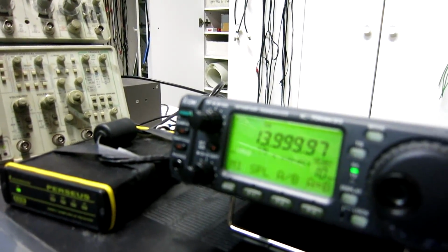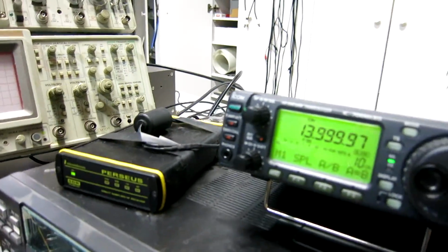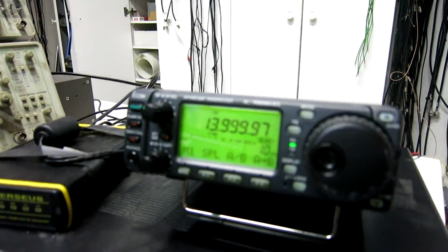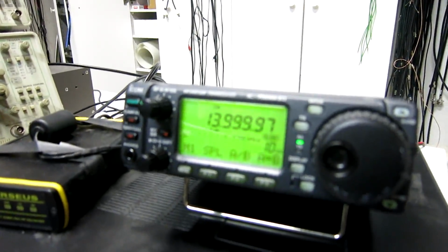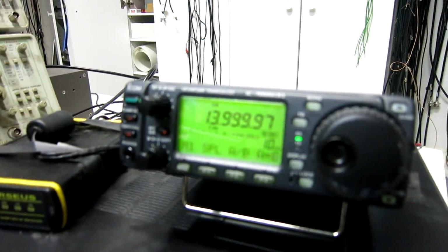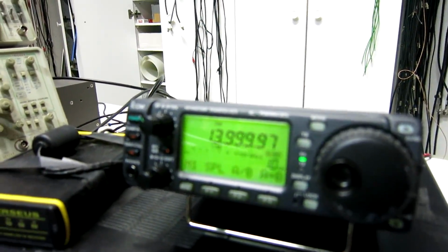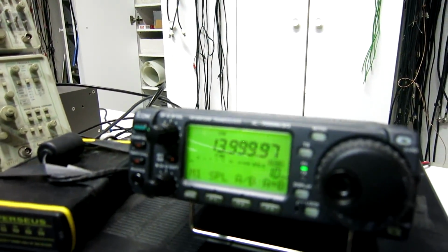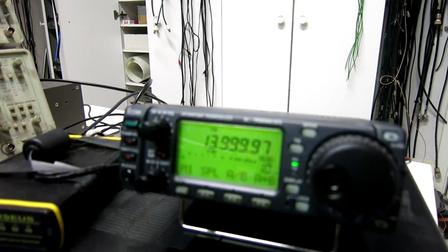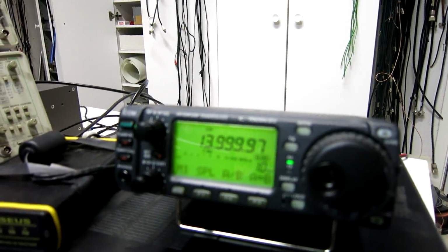And this is clearly interference. So this little radio, it's somewhere maybe 7 or 8 or so dB worse than the two other high dynamic range radios. And that is with the 10 dB dummy load in front of the Icom to make the noise figure the same as the other two radios.